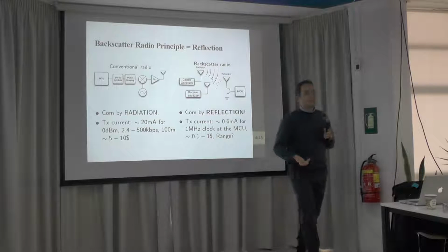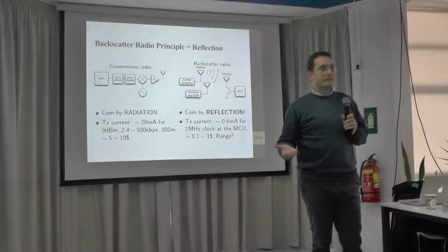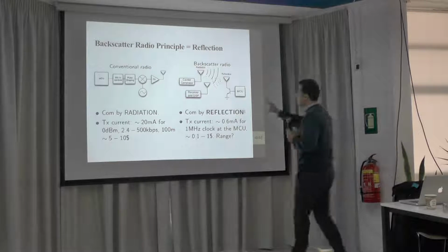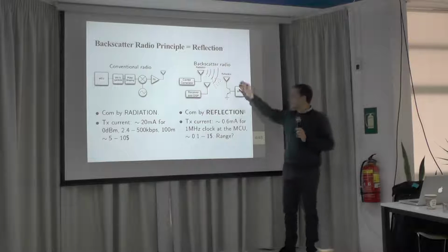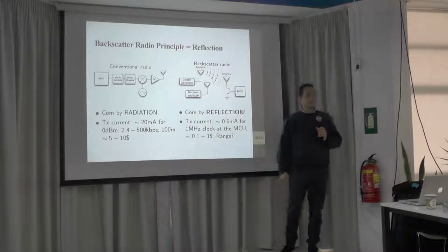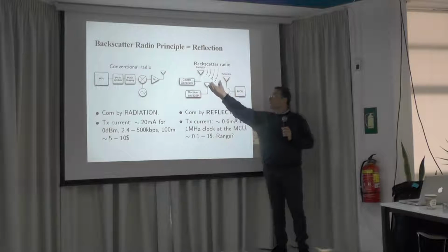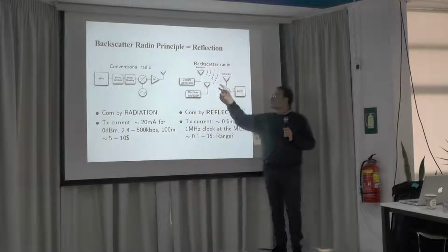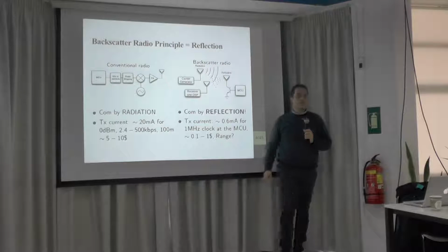How much energy do you need in order to switch a transistor on or off? A minuscule amount of energy, right? So with this principle we can create ultra low power communication using an antenna and a switch at a cost below $1, a fraction of $1. And because this is extremely low power, you can essentially harvest energy from the illuminating field. So this device not only illuminates this antenna, but also can provide the power that this module needs in order to operate.